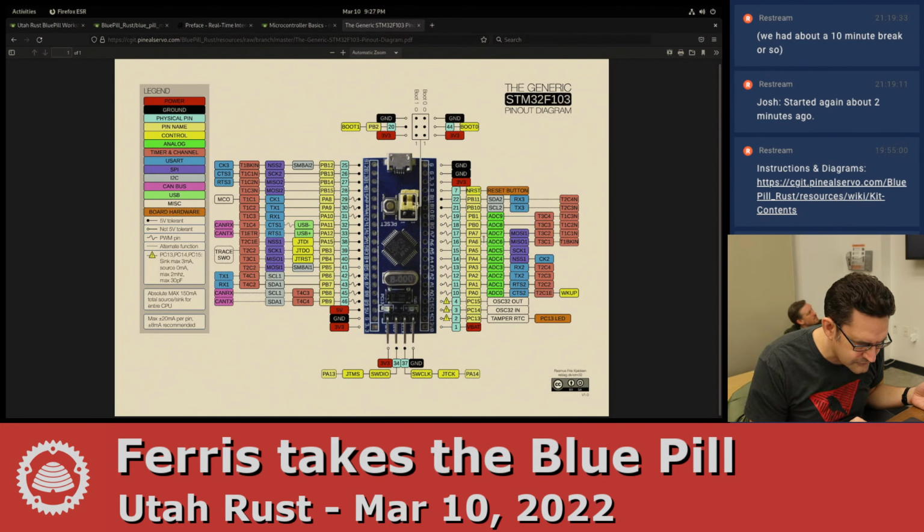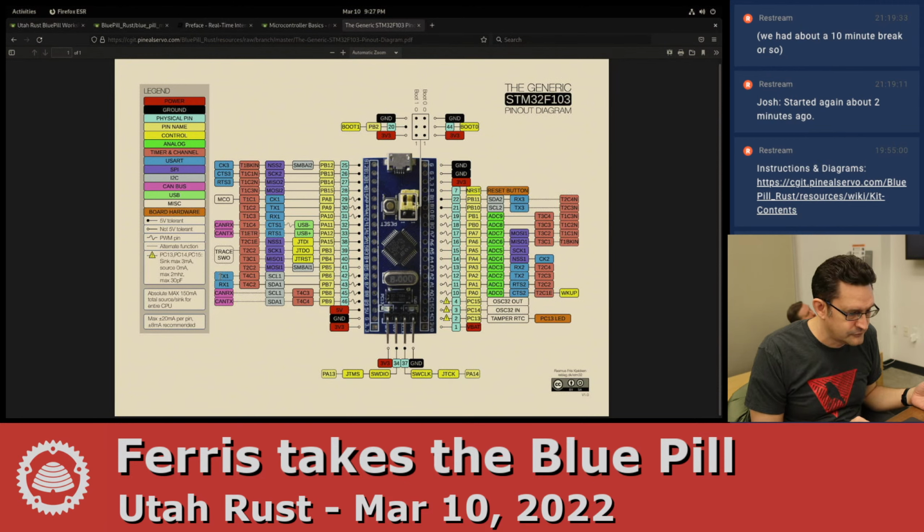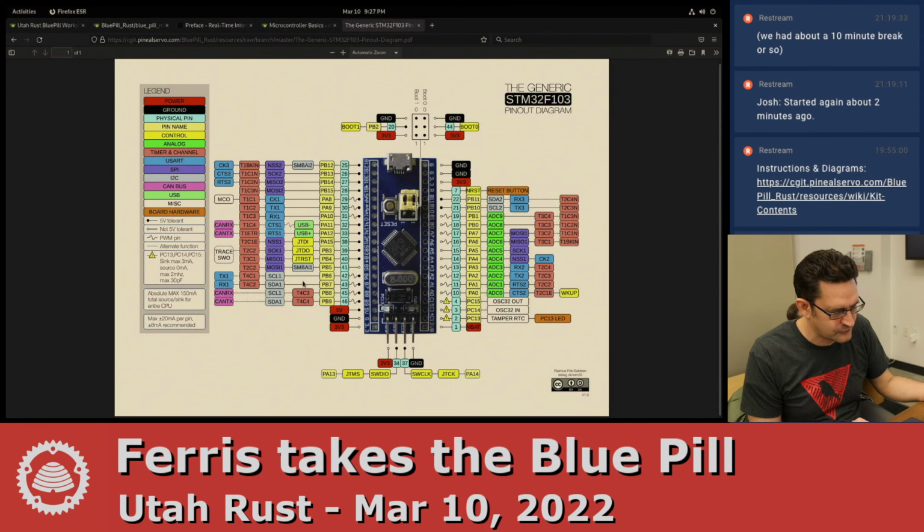But if you use those pins for that, you cannot use them for the timer. You can't use them for the UART, TX and RX1. Oh, okay. And you also can't use them for timer 4 channel 1 and 2. Yes. So you get to pick one purpose that those pins serve. They can be just regular GPIO pins, or they can be I2C1. See, these have exactly the same name. You can route that peripheral to either pair of ports.